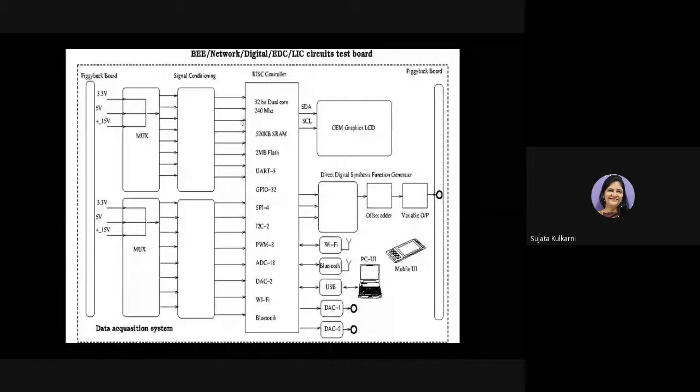So that is your choice of choosing the power supply. That's what I called multiplexing. Actually, it's not a multiplexer, but it's a choice of selecting any of those operating voltages. And then once again, the challenge is bringing it to acceptable voltages, that is, no negative polarity. Everything should be shifted to the positive side, and that too up to 3.3 volts, because most microcontrollers have inbuilt ADCs where the operating voltage is 0 to 3.3 volts.